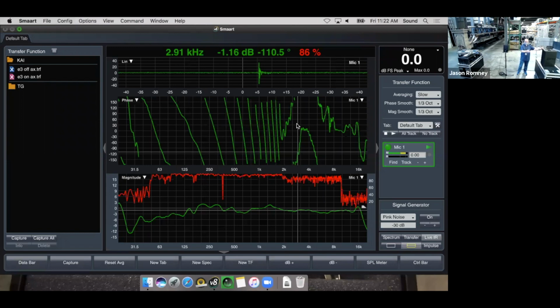Right? You see this air between the loudspeaker and microphone? That's going to take a certain amount of time for the sound to get from here to there. How much time? I don't know. This looks like 1, 2, 3, 4, 5 feet or so, 5 or 6 feet. So we would expect at least 5 or 6 milliseconds, right? For the sound to travel that distance, plus the millisecond that's in the amp. So there's about 7 milliseconds of time that we've accounted for that is probably going to be different between the two sounds here. And that would certainly explain a huge impact on the phase response.